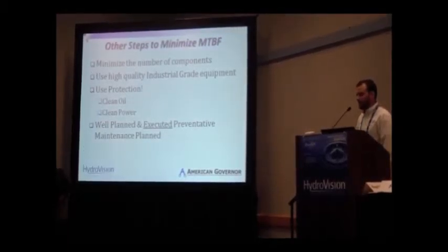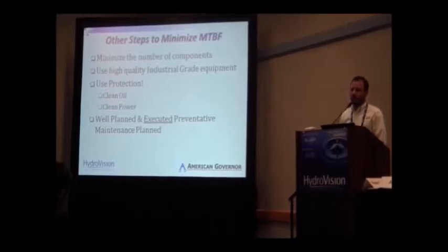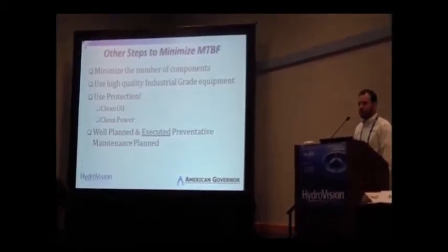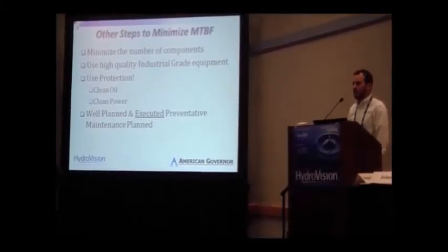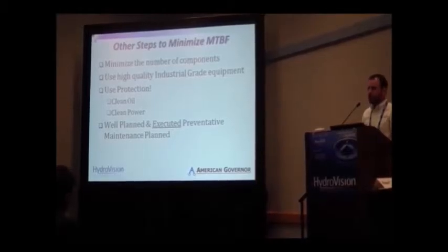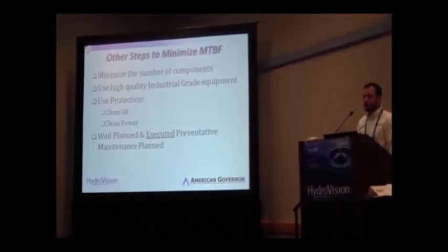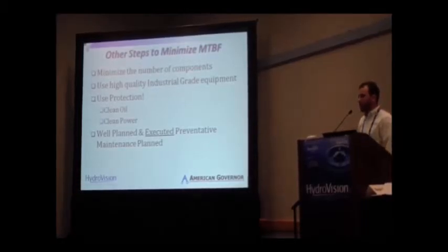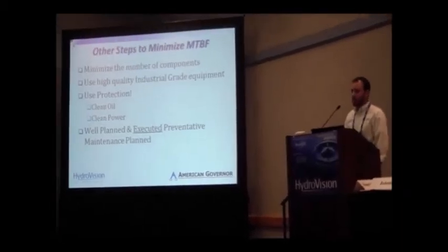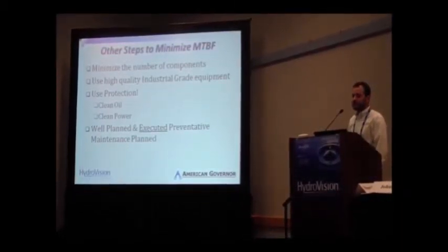Now, on top of deciding what level of redundancy, there are other steps you can take to minimize your mean time between failures. One thing you saw as a trend is that as we increase equipment, you'll have more equipment failing. So minimize the number of components across the board during your design. Use high quality industrial grade equipment. Use protection, clean oil, clean power, filter your oil. And then a well-maintained, well-executed preventative maintenance plan will minimize the failures that can take your system out.